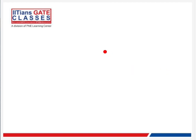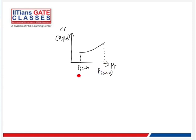So the next one is called a fuel cost curve, which is an important factor. This is our cost, in rupees per hour, and this is our P_i. This is our P_i minimum and this is our P_i maximum. Since we have a quadratic relationship, it will not be linear. If you remember, this was one of the conditions that we looked at, P max and P min. This is called a fuel cost curve.